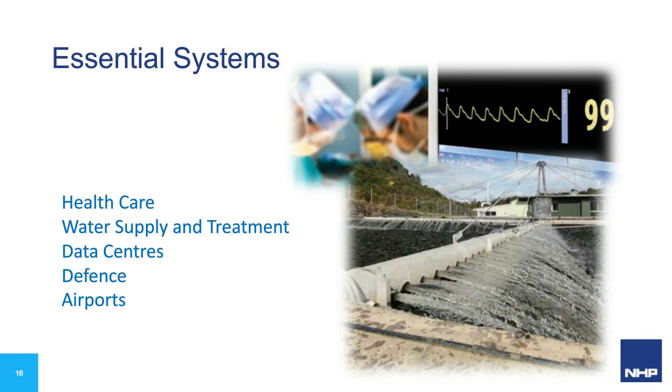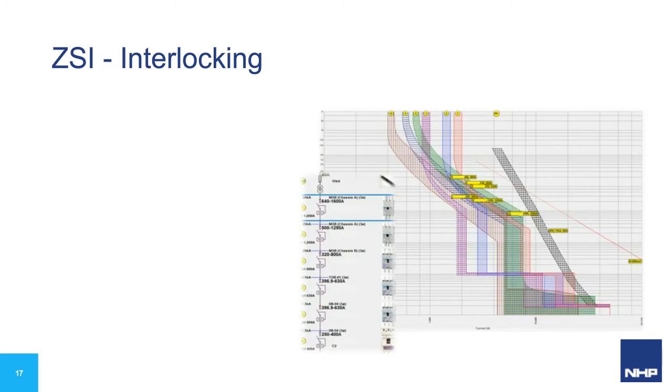In the example shown earlier, breaker adjustment is just not possible even if we cheat and adopt a single line depiction and disregard setting, component and operational tolerances. One of the only ways we can overcome this is through a method called ZSI, or Zone Selective Interlocking.